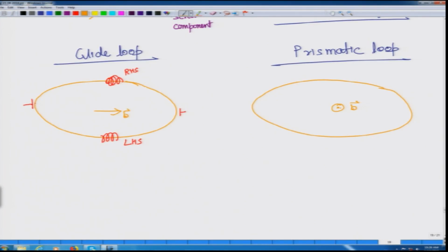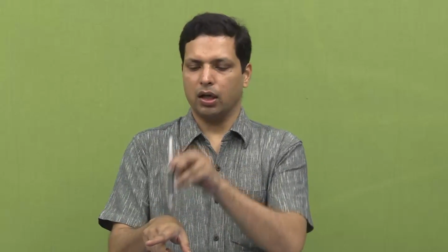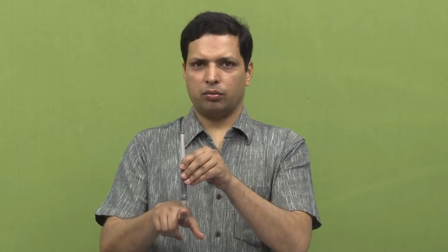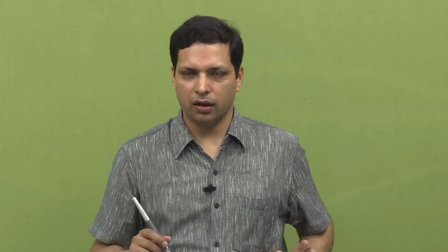Now, what does that mean? Can you imagine how the dislocation here should look if you have the Burgers vector over here? First of all, you realize that this is the Burgers vector and the line vector is like this. So, the line vector is moving on this particular plane, it is rotating at different points, but the Burgers vector is always like this. So, what does this mean? That the Burgers vector is always perpendicular to the line vector. Now, that is very surprising. So, in a loop we have a completely edge dislocation because the Burgers vector is always perpendicular to the line vector. So, this is a very interesting loop.